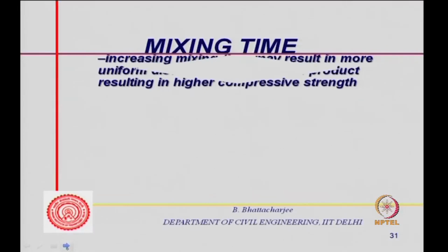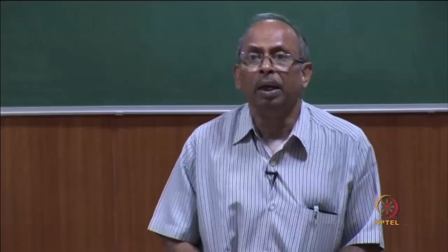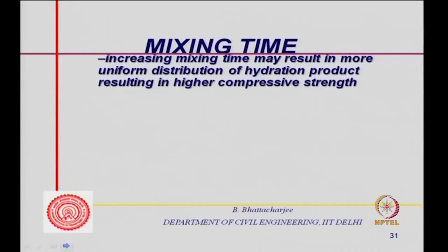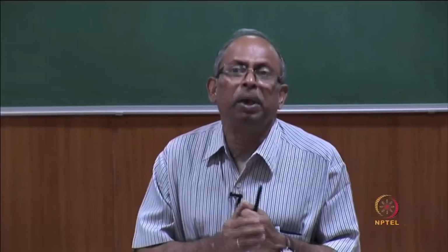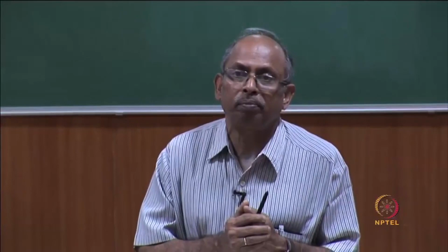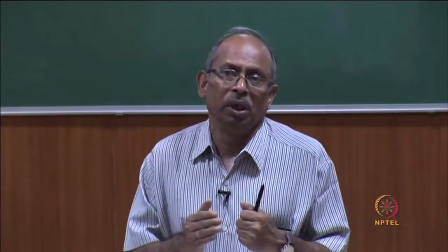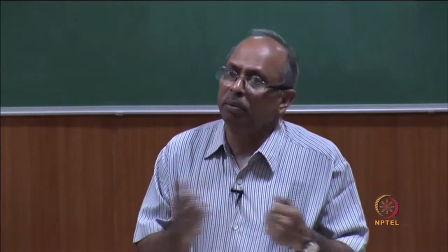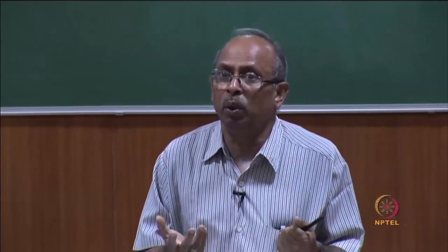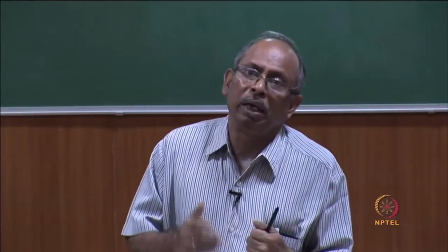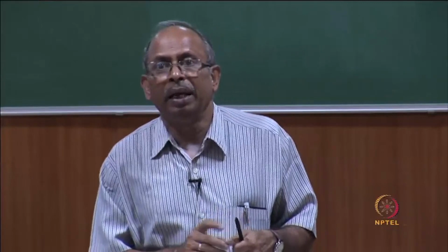But first of all, let us see why I need sufficient time, because increasing the mixing time may result in more uniform distribution of hydration product, because it causes abrasion over the surface of the aggregate, and therefore removes the hydration product, and some of the hydration product then further gets exposed to water. New hydration product would get deposited on top of the aggregates and so on.